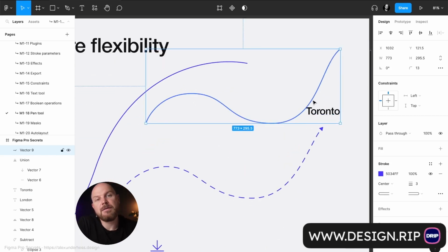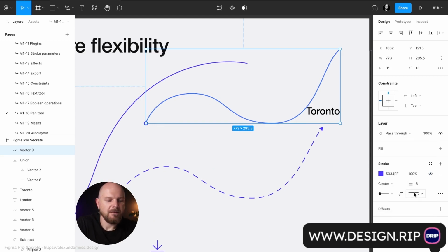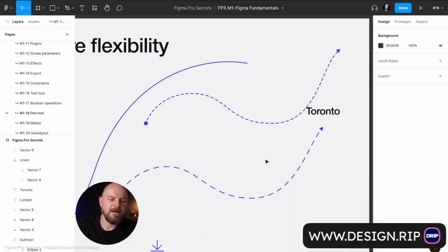This is how I created this curved line. Then I go, you already know from the line tool how to do that. Go here, change some parameters, and then I go to advanced settings of the stroke, click dash, and here in dash I press 10, dash 10, gap 10, done.